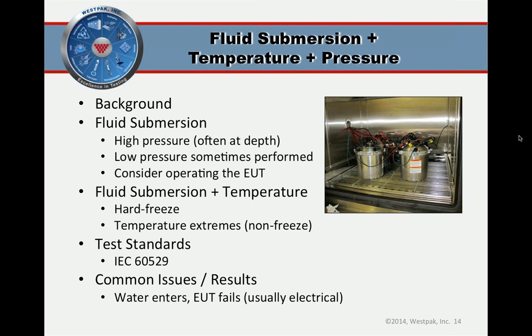The other extreme test we've done is a non-freezing test. So we'll use a water glycol mix, and we'll go ahead and cycle it between minus 40 or 50 degrees C up to plus 80 or 90 degrees C, and you're doing a huge thermal stress on all of your components while that fluid could be forced into the product, but not actually doing a hard freeze.